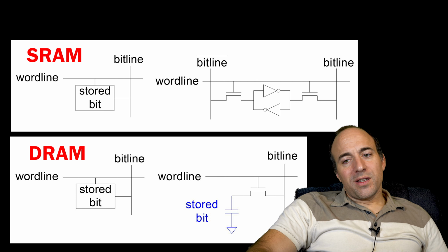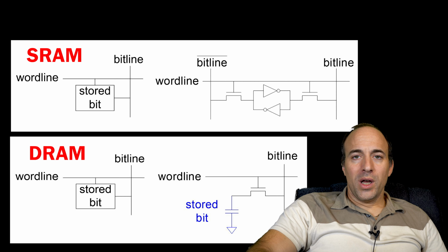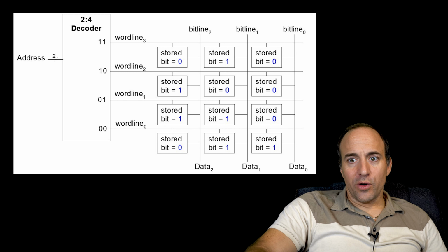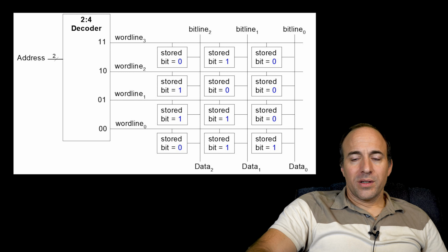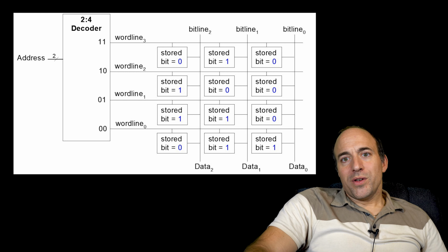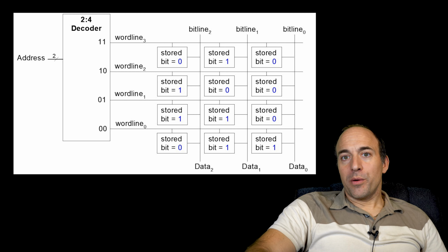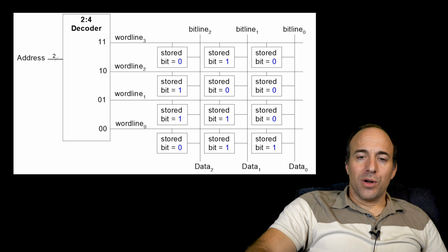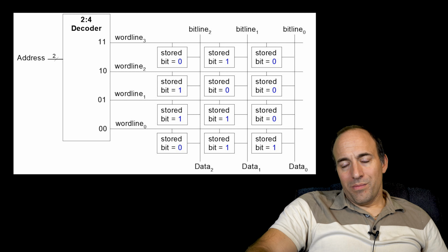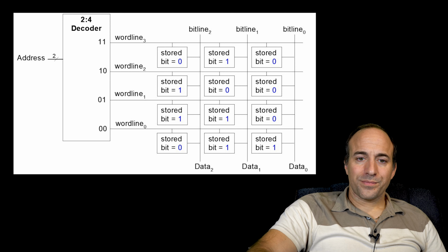The access time is affected more by the size of the decoder that converts the memory address to the word lines. Larger memory arrays require a larger decoder because there's more word lines, and the latency of the decoder scales with its size. This is why larger memories in general are slower in access time as compared to smaller memories. Since DRAMs are usually larger than SRAMs because they have a higher density, in effect that causes DRAMs to be slower than SRAMs.